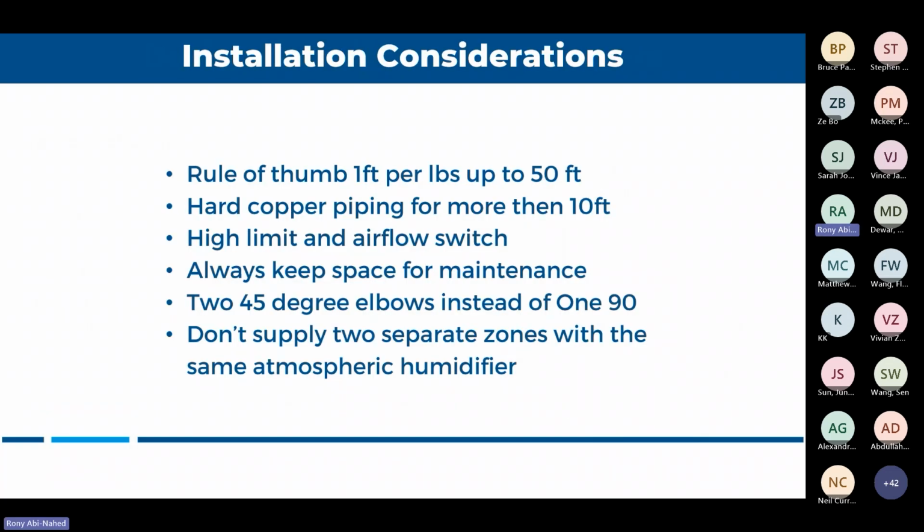So, a couple of installation considerations that you need to keep in mind. The first one, I get a lot of questions about it. How far away can I go from the generator to my grid? Let's say my grid is in an air handling unit and I have an electric unit in the mechanical room. How far away can it be? You can't go more than 50 feet, to make it easy.